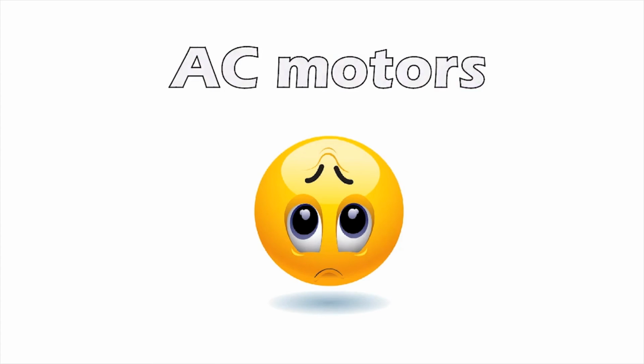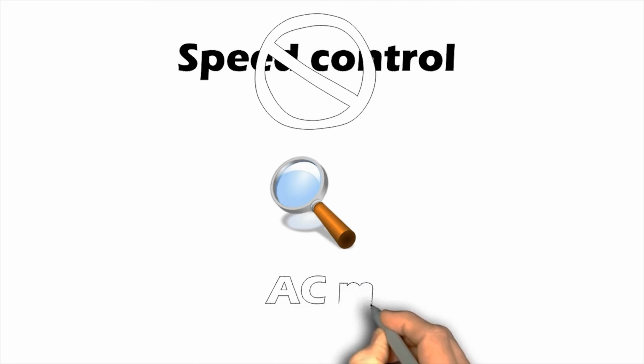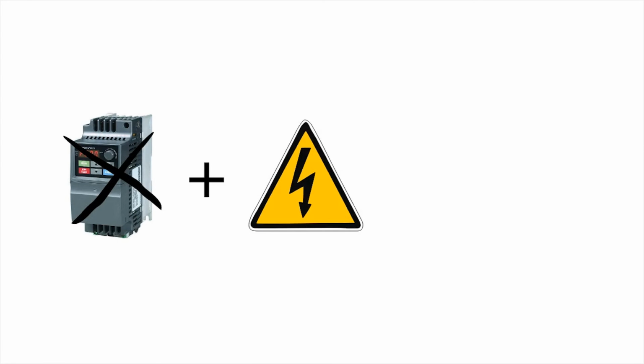With all that being said, however, AC motors are not completely useless. Applications that do not require speed control and some other specific applications are better off with AC motors. This is because AC motors that do not need to control the speed won't need a VFD, due to the fact that they can run on the AC current alone as the frequency is already varying. This makes it more cost-effective to use an AC motor in such applications.